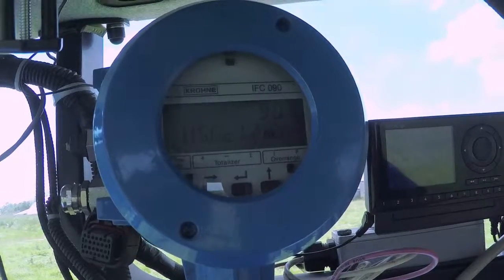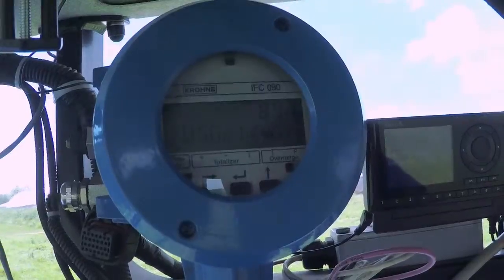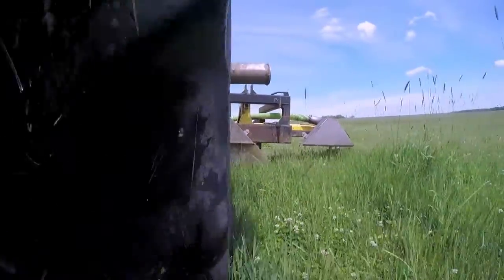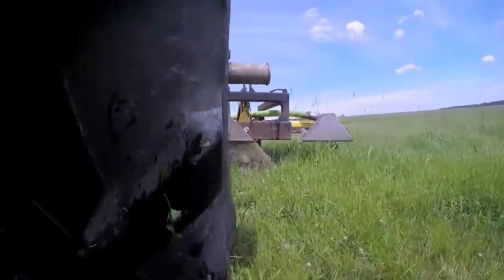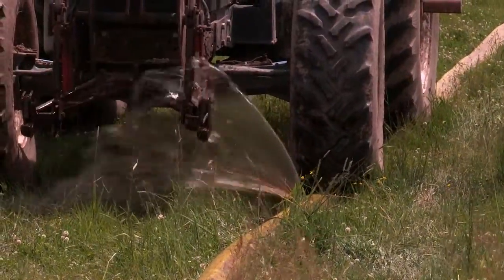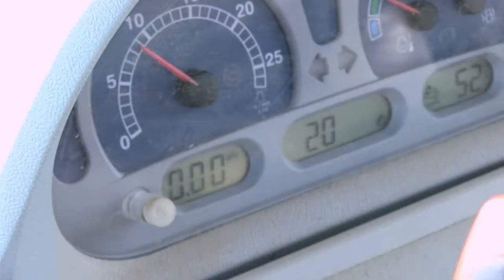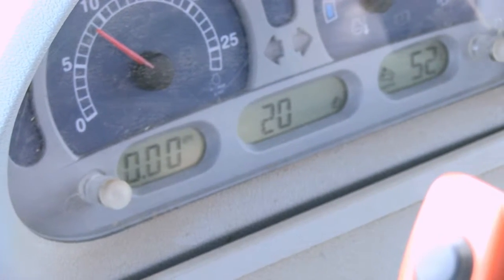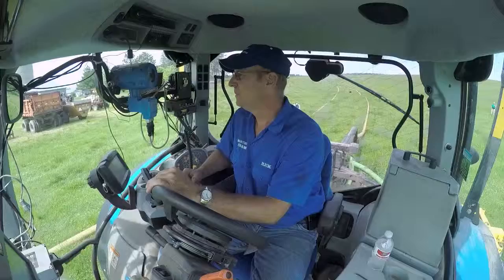Watch the flow rate, which shows the gallons of liquid flowing through the meter on the application bar. Look for any deviation or variation in the output you expect to see, because that could be telling you of a break, leak, or incident. Your speedometer or GPS display shows your ground speed as miles per hour, which should stay as constant as possible. Consistency of the flow and speed is key.